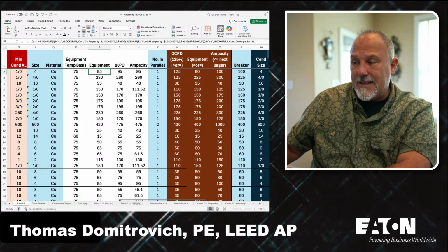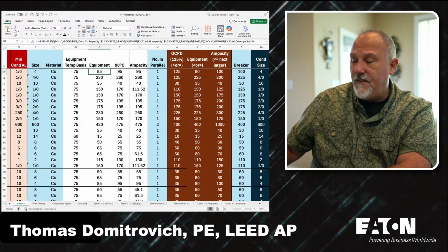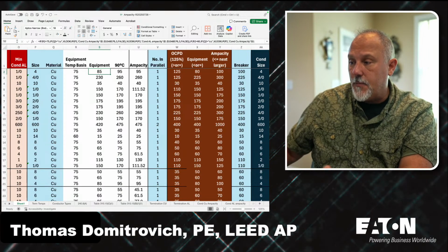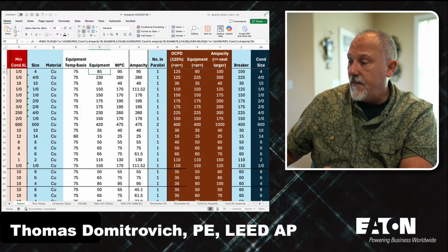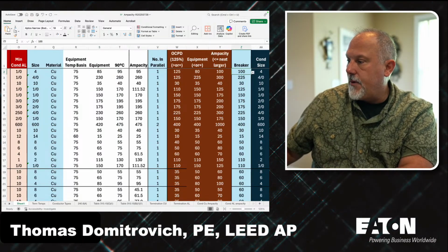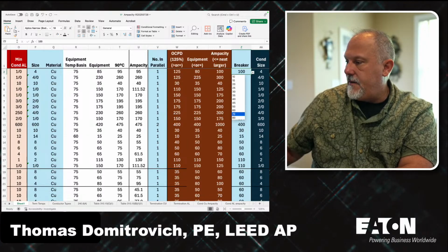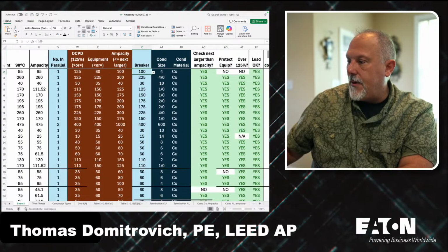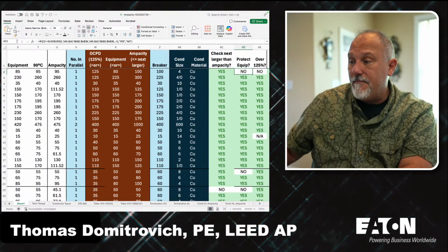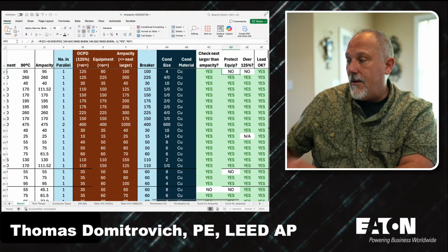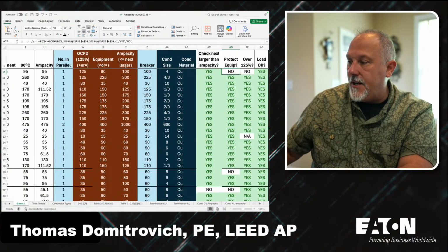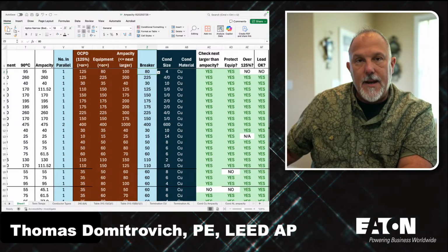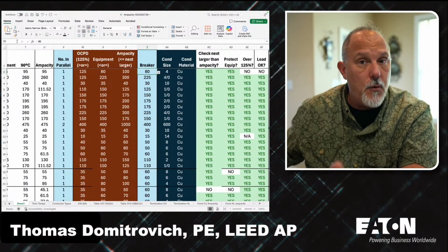If I put a 4-gauge conductor and I change this overcurrent protective device to 100 amps, 100 amps has to be less than or equal to the equipment. That 75 degrees C equipment, it has to be less than 85 amps. So I would have to put like an 80 amp breaker on it if one existed. What are the standard breaker sizes? 85? Yeah, I'd have to put an 80 amp breaker on that. If I don't have an 80 amp breaker, I'm not protecting the equipment. Now, forget about the load, but that is a no. If I put this down to an 80 amp breaker, boom, I'm now protecting the equipment. And that's all based on 240.